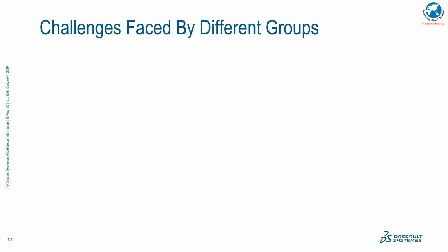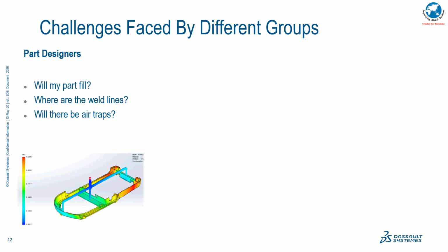Let us discuss the various challenges faced by various groups of people. The part designer needs to ensure whether their part gets filled or short, and where the weld line will occur. They need to avoid weld lines in load-acting zones and avoid air traps to reduce burn mark issues.